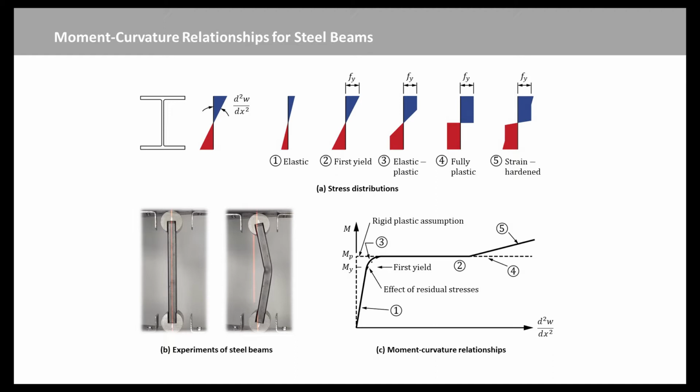The strength of a steel beam in the plane of loading depends on its section properties and on its yield stress Fy. When bending predominates in a determinate beam, the effective ultimate strength is reached when the most highly stressed cross-section becomes fully yielded so that it forms a plastic hinge.